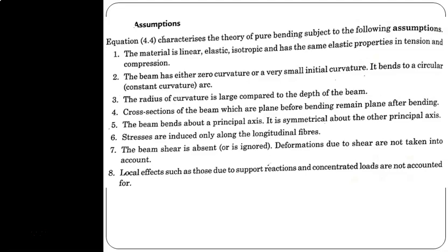The beam bends about a principal axis. It is symmetrical about the other principal axis. Stresses are induced only along the longitudinal fibers. The beam shear is absent or is ignored. Deformation due to shear is not taken into account. Local effects such as those due to support reactions and concentrated loads are not accounted for.